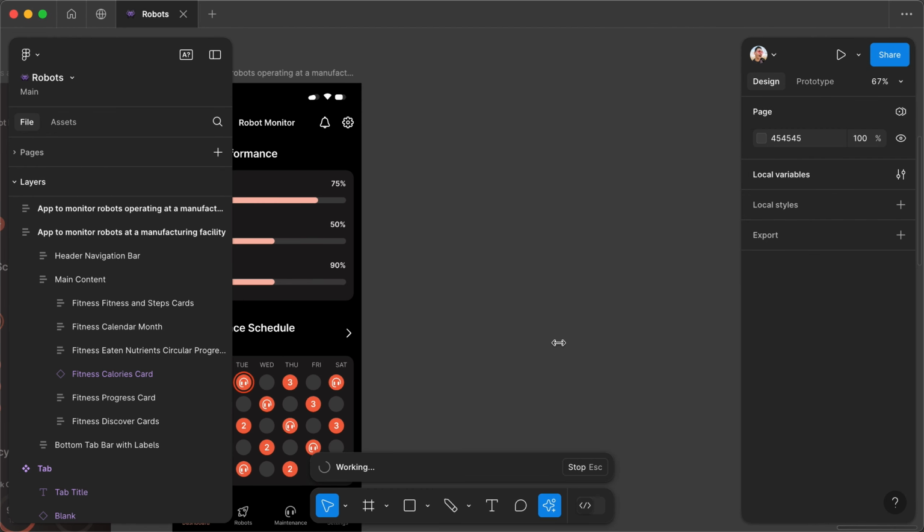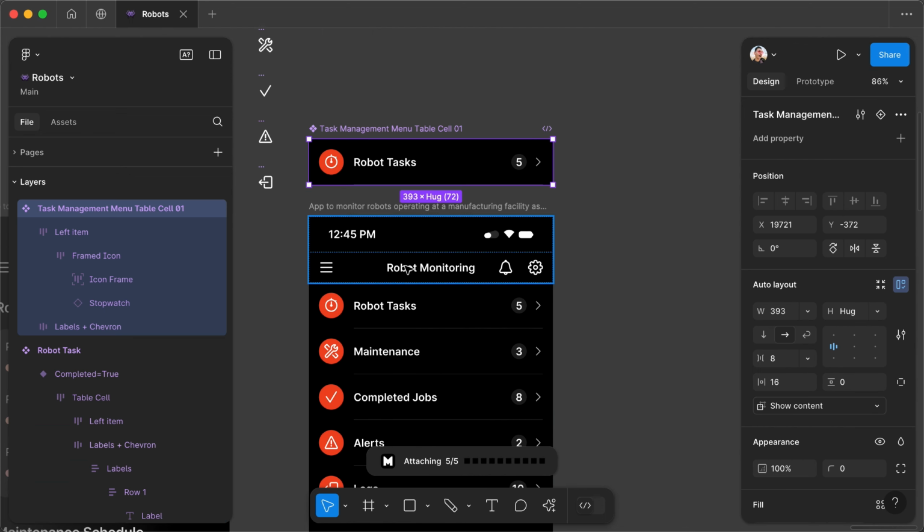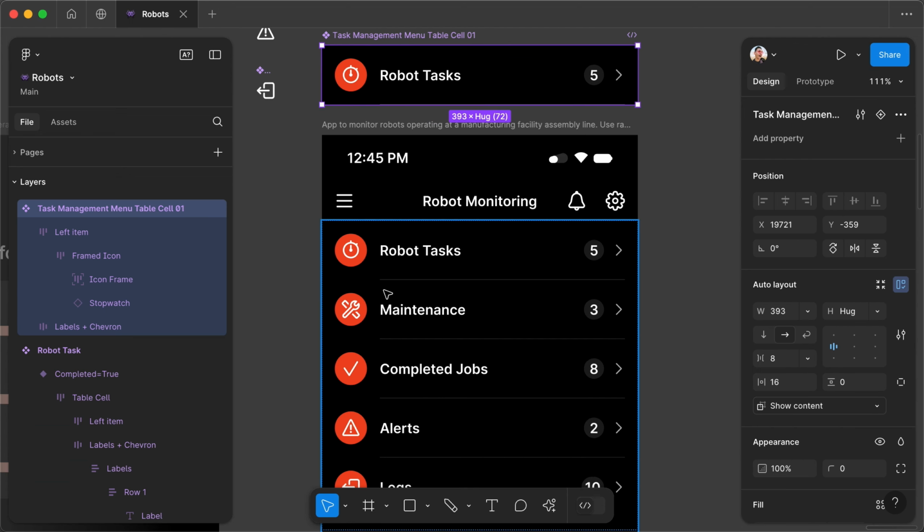Now that the items contain icons as instances, which can be swapped, let's turn them into a single component. Like in the previous examples, use Master plugin Create Component from Objects feature. I simply press Option Command P or Alt Ctrl P on Windows to rerun the plugin. All the icons are preserved correctly now. Let me make some changes to this component, like removing the unnecessary counter object and making the icon red.